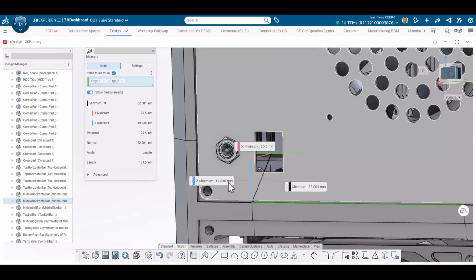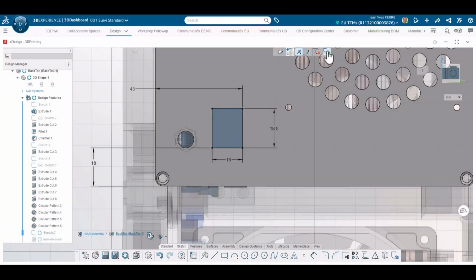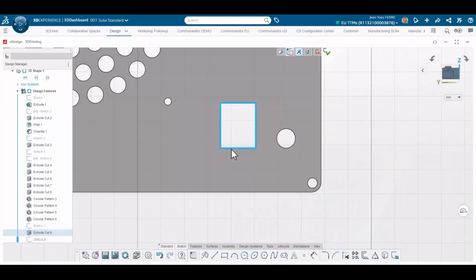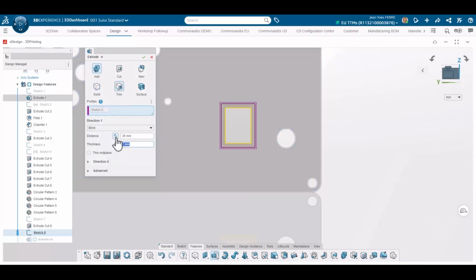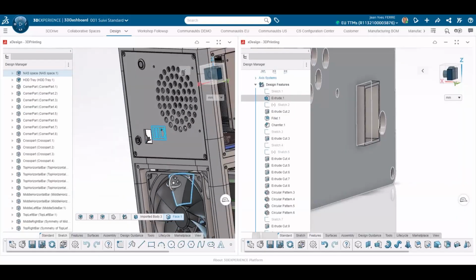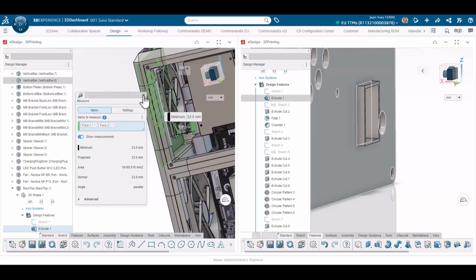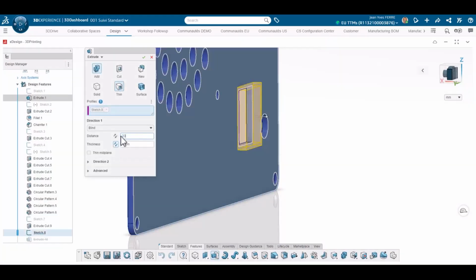After correcting some dimensions because I was slightly off, I notice another potential issue. The plug is deeper than the panel, which could make connecting the cable tricky. To fix this, I add guiding walls around the plug using thin extrusions. I carefully measure the distance between the panel and the plug and add clearance to avoid assembly issues. These walls will ensure the cable connects easily despite the depth.